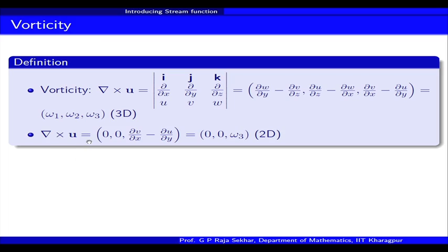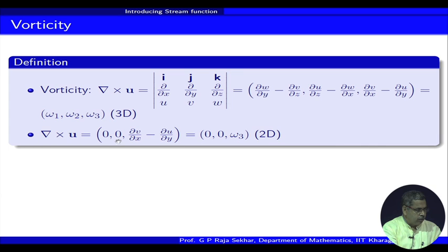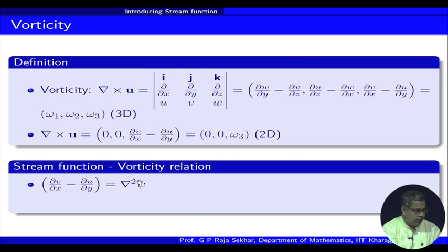So, that is vorticity. Similarly, if you have only 2 dimensions, then for any general u, v, w, you have only one component. That is given by this, so we call it only omega 3. So, we have 2 scalars: one is the stream function, and curl u can be represented in 2D as another scalar, whereas in 3D omega is also a vector.